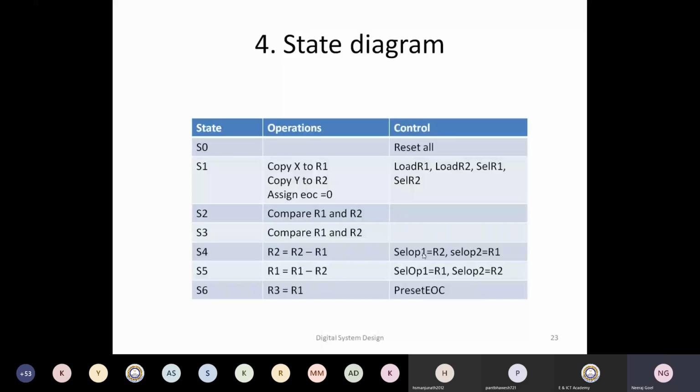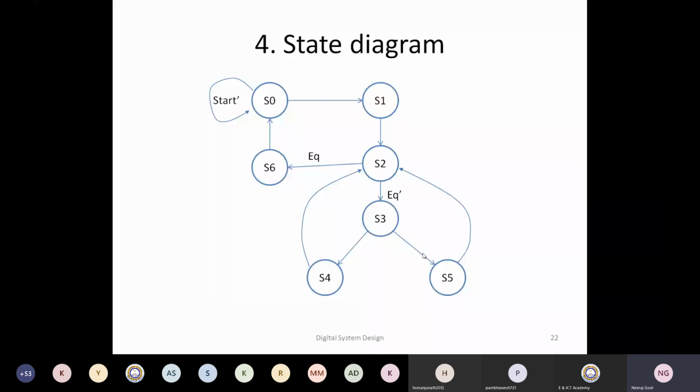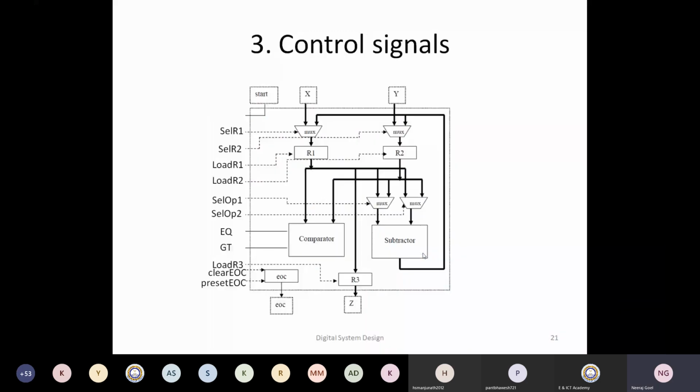So one more thing to be explained before we go into the demo is that we have divided our whole circuit into two different parts: the data path and the control path. As we discussed yesterday, the data path is important to determine the latencies or the clock cycle, while the control path will determine in what particular clock cycle the circuit will be in which state, doing what task.